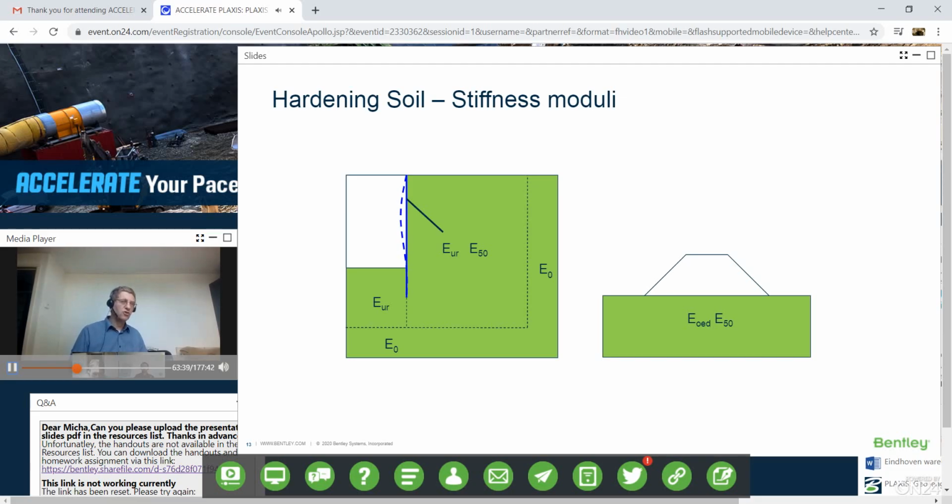If you get closer to the toes, then of course you see more deviatoric loading, because the embankment pushes the subsoil down, and the subsoil will actually go horizontally away in either direction. Close to the soil surface, the horizontal movement is quite big. At deeper depth, the horizontal movement is quite small. Therefore, you have a deviatoric effect. So closer to the toes of the embankment, E50 is the most important stiffness parameter. In the middle, E odometer is.